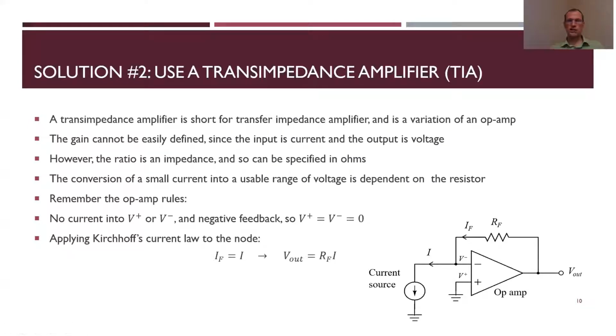So for this one, it's kind of tough to figure out. Usually we want to find what the gain is, gain being the voltage in divided by voltage out. I said that backwards. The gain being the voltage out divided by the voltage in. But in this case, I don't really have a voltage in, I have a current in. But what I can do is take that current and that V out voltage, and voltage divided by current gives an impedance just by Ohm's law.